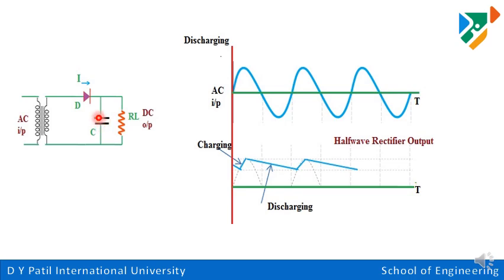The flow of current always chooses a low resistance lane. So when the current reaches the filter, the AC component experiences low resistance and the DC component experiences high resistance from the capacitor. So the DC components flow through the load resistor.